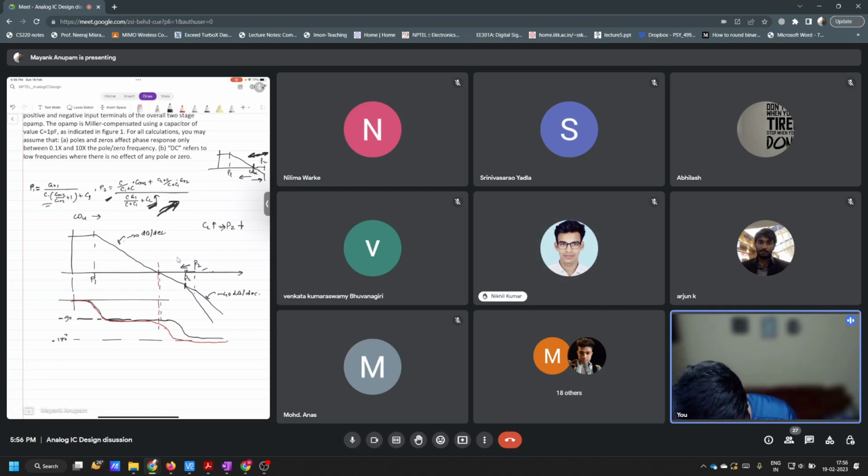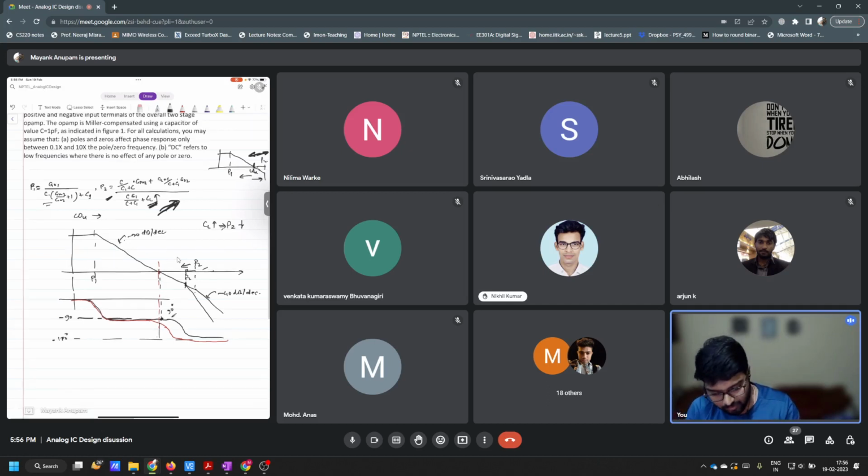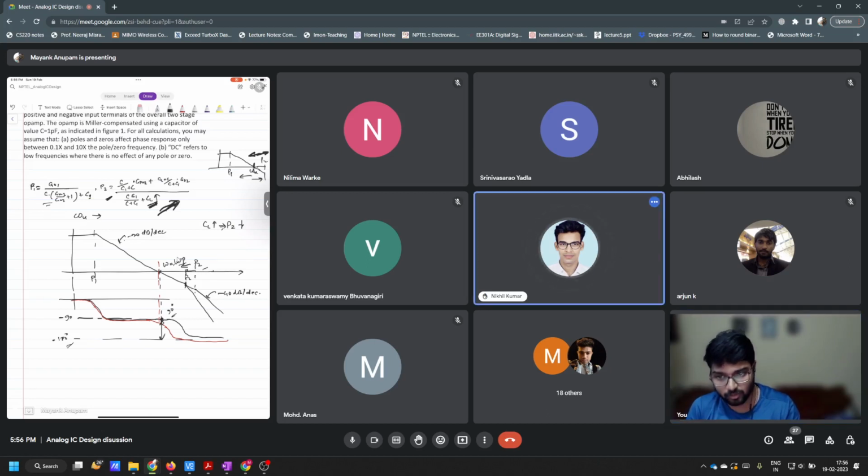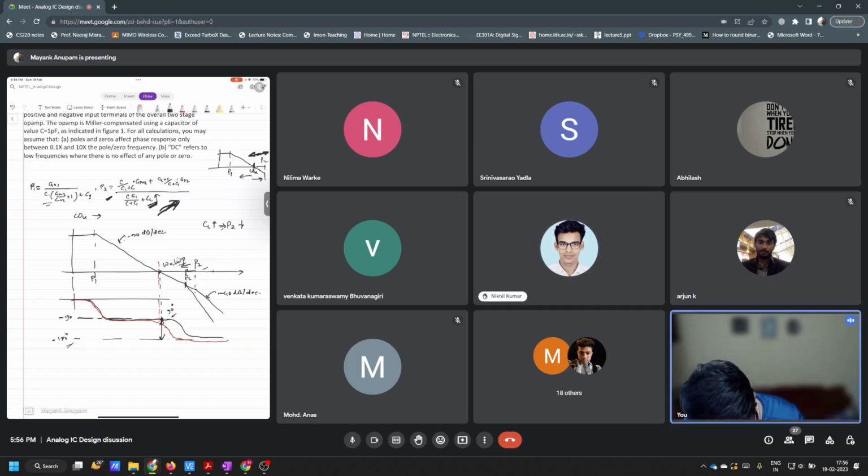Earlier you had this 90-degree phase here, and you had a phase margin of 90 degrees, but now the phase margin is slightly poor. Earlier your phase margin was what? Earlier phase margin was 60 degrees? 90 degrees or 60 degrees? No, in this figure I'm saying. It is the difference between 180 degrees and the place where your omega u becomes omega u loop, right? At this place you check what is the phase, and that is why the phase here looks very close to 90 degrees, right? But in the red phase curve it becomes slightly lesser, isn't it?